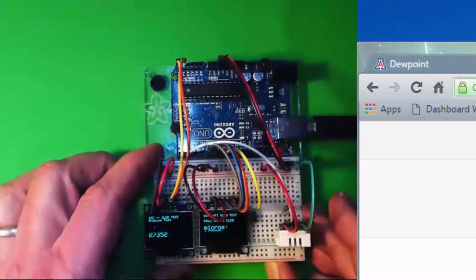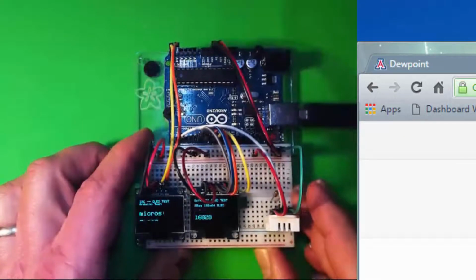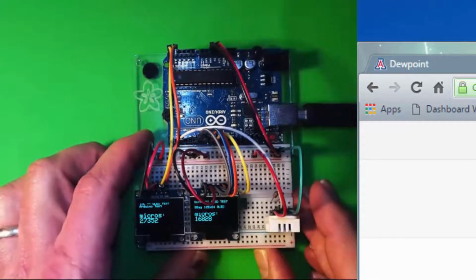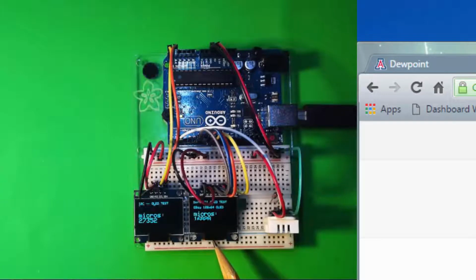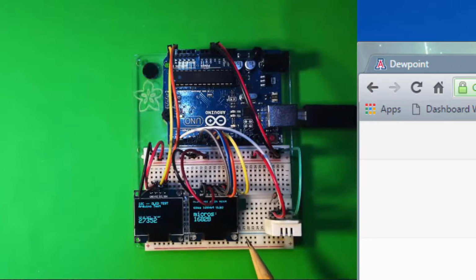So both of them are very viable options. The I2C is a little bit easier to get working oftentimes, but if you've got a lot of other I2C devices on your data logger, sometimes you can have conflicts and it's slower. So I guess if I had to make a recommendation, I would lean toward the SPI versions. So let's continue moving on with this SPI version and see if we can connect this relative humidity chip to it and collect some data and display it on the screen.